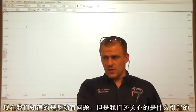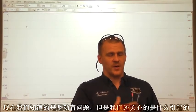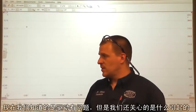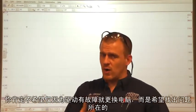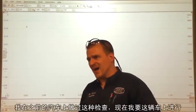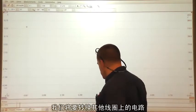In our scenario, what we have so far, 9.9 times out of 10 we have a driver issue, but one of the things we need to be worried about is what cooked the driver. You never want to just replace a computer because a driver failed. You always want to check it. I've done this before on previous cars. We're going to do it on this one.